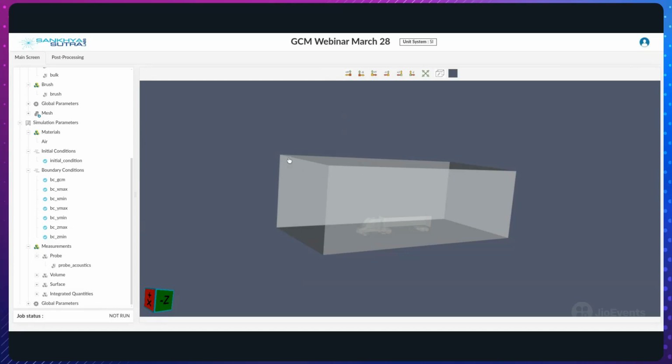Similarly, we also have a facility to be able to print surface data, which is basically printing all points that correspond to any particular patch in your STL that you might want to monitor the data for with time. For example, you might want to print all points that correspond to the surface that is your tractor trailer to be able to post-process that data to be able to obtain the pressure coefficient, which you can then compare against reference data in your solution.